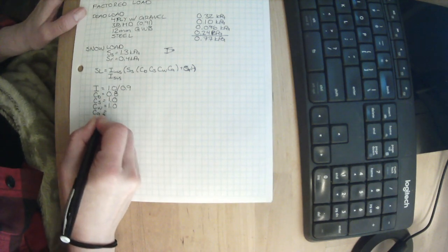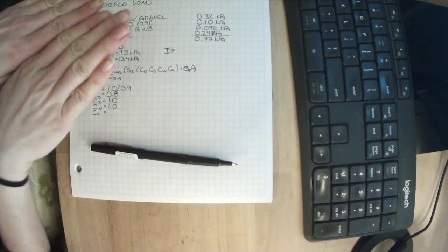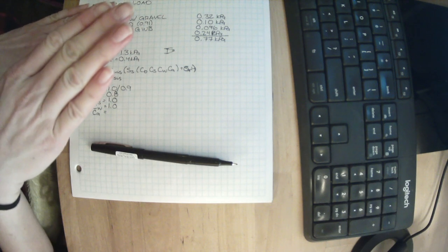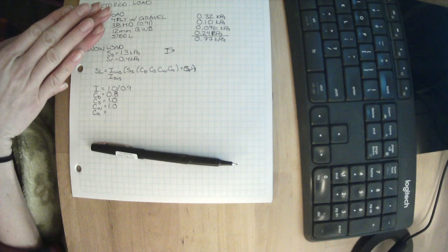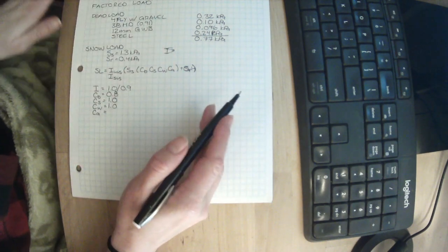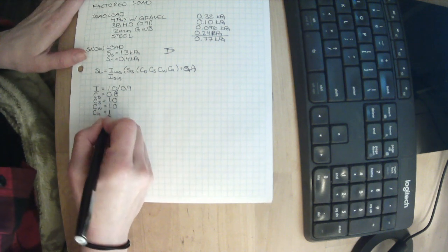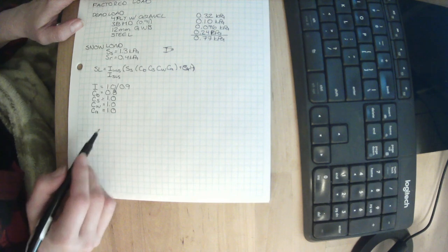And then CA is our accumulation factor. That would happen if our canopy was low and our existing building was high and snow blew off of it and piled up on the canopy. It said in the equation that the two roofs were at the same height, meaning that our CA would be 1. So now we can calculate